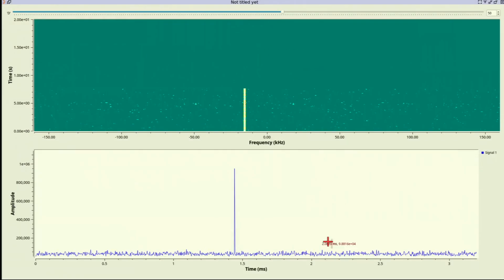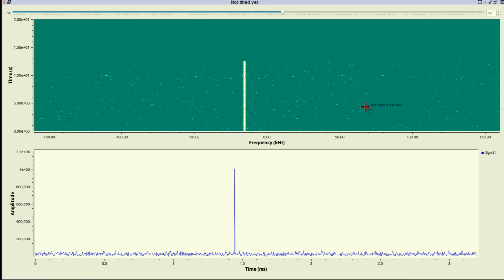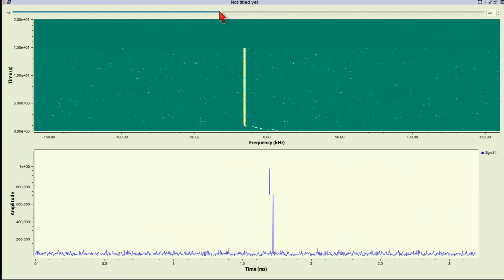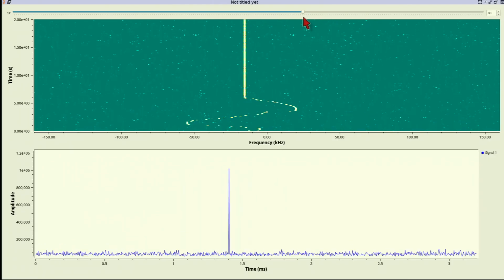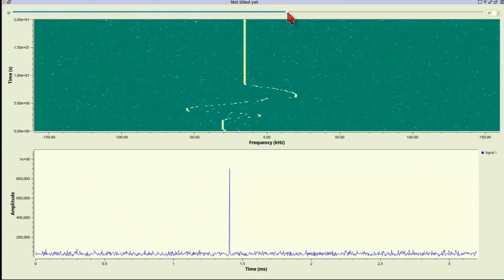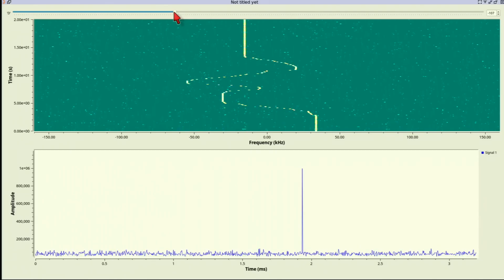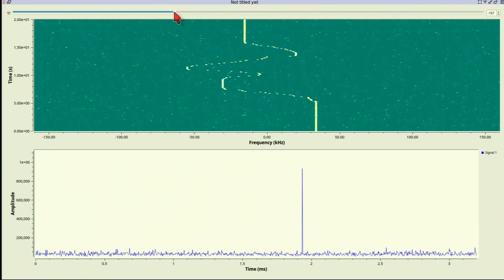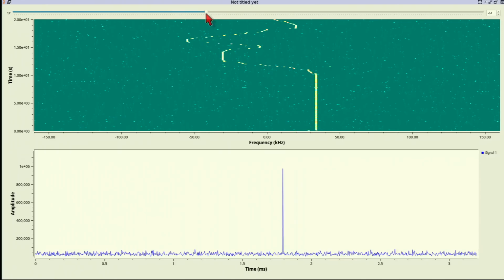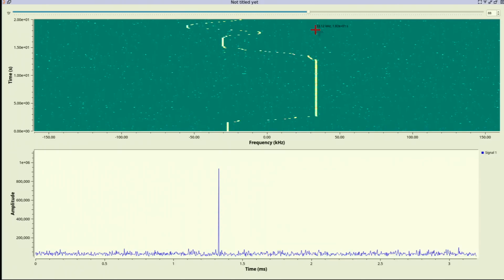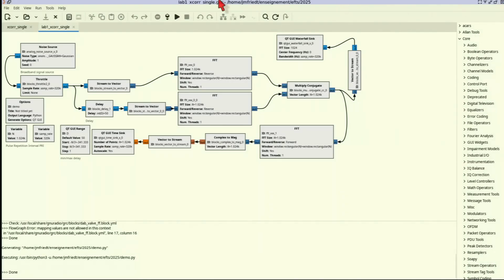And that's the output. So you see here we're broadcasting a noise. The noise is detected with a 0 delay. And if I move the time delay here, you see your cross-correlation peak moving left and right as I'm introducing the delay. So what I'm doing here is introducing a delay between the reference and the surveillance channel. And you see on the bottom the inverse Fourier transform of the product of the complex conjugate of the Fourier transform of a signal and the Fourier transform of a surveillance, and you see the position of a correlation peak. So this is a demonstration of how you actually calculate a correlation in a software framework that does not know what a correlation is. If you search for correlation in GNU Radio, you will not find it.